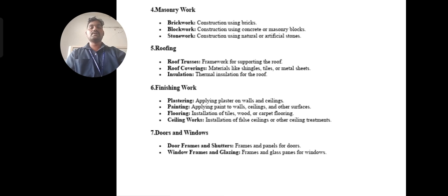And then flooring, I want to explain the flooring very well here. For example, if you want to calculate the cost of the flooring, first we need to measure the area of the rooms where we need to install the flooring, including the skirtings and any dias. We need to calculate each and everything very accurately. And then after calculation, we need to take one size. So for example, if for flooring you want to install tiles, then what is the dimension of the tile.